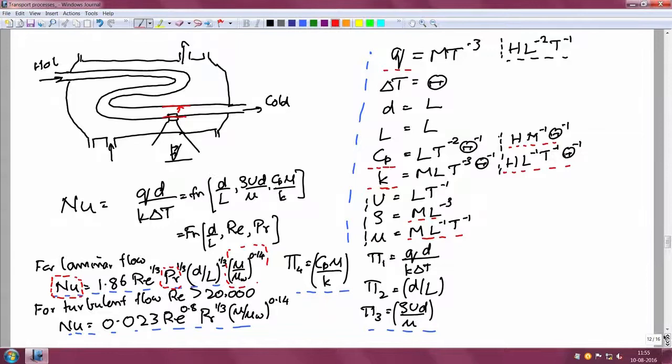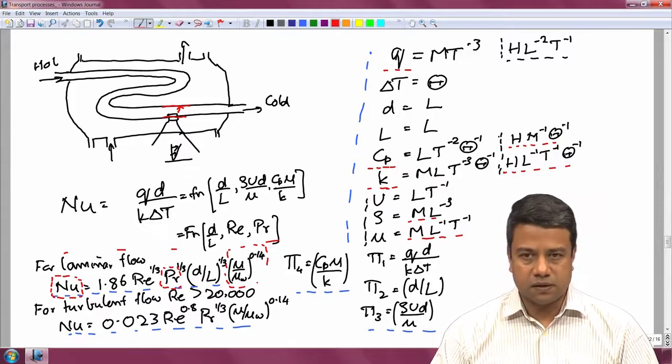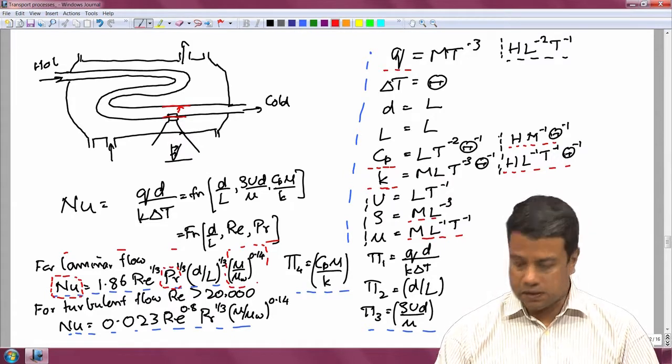As you recall, we did the dimensional analysis for the heat transfer across a surface of a heat exchanger, and we got a relationship between these quantities, the Nusselt number, the Reynolds number, the Prandtl number, and so on. A considerable reduction from the complexity of the original problem, without a doubt, but we still do not have a good idea of what these things called Reynolds number and Prandtl number mean.